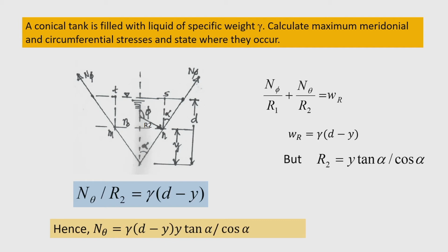Then it will also have a slanting wall, that is like a conical shell, like a frustum of a cone, and then it has a spherical bottom. Instead of a flat bottom, it will have a spherical bottom. So, all types of surfaces of revolution are involved in this type of elevated water tank, generally known as the Intze type of water tank. So, conical shell analysis is also necessary when we apply it to this liquid retaining structure. Okay.